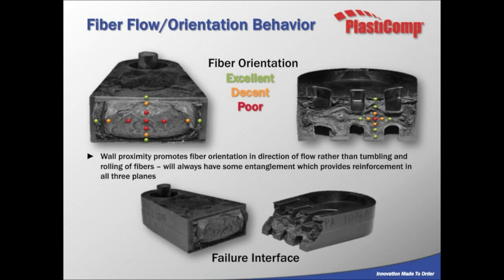Now this was beneficial in several ways. The part was lighter, it needed less material, so it was cheaper, and the cycle times were faster, and we had less internal stresses. And the part was overall stronger. So that's very contrary to how somebody might think if they're used to the metals industry, where they just want to make the part thicker if it's, let's say, overstressed. That's not the case. Actually, there is a diminishing return once again if you get too thick, and it actually becomes weaker.